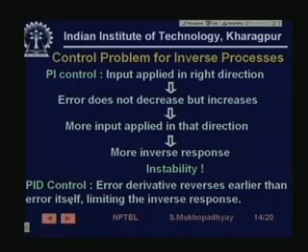On the other hand, a PID controller not only sees the error and its integral, it also sees the rate. As we have seen, the rate will reverse quicker, so the PID controller is likely to give a slightly better response, because it will try to give correct inputs much faster because of the derivative reversing. So this is just an aside. But let us see first how we can compensate for this inverse response.